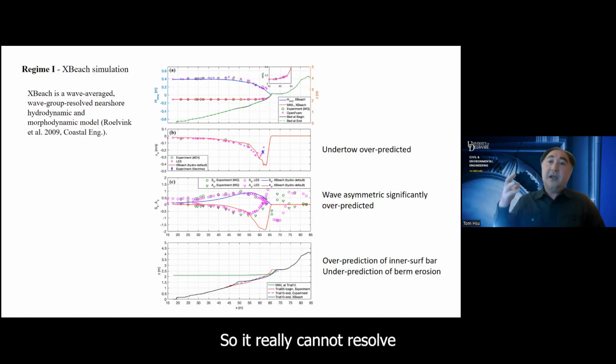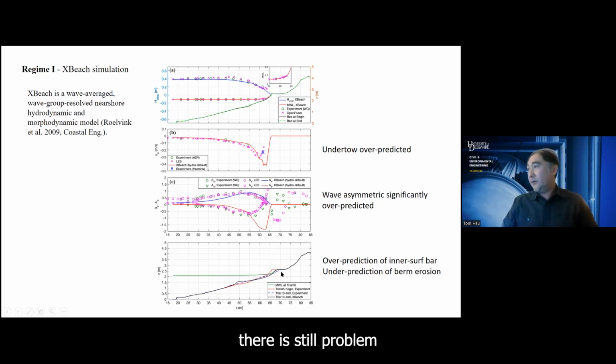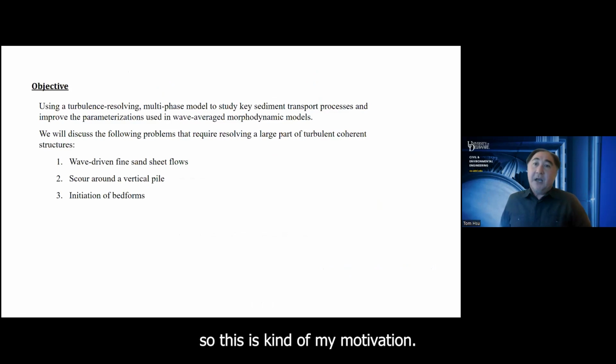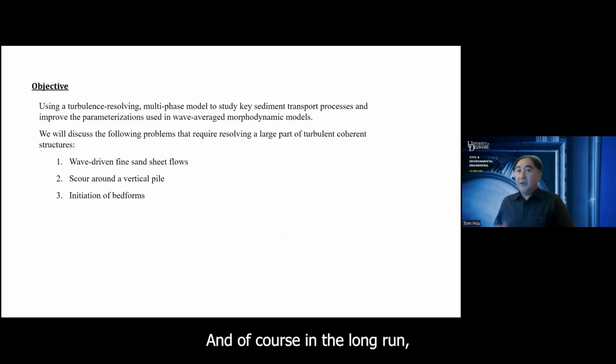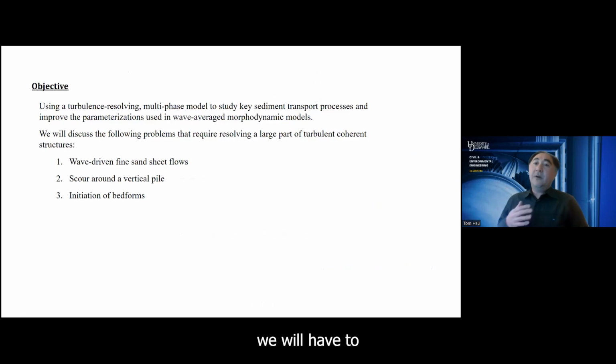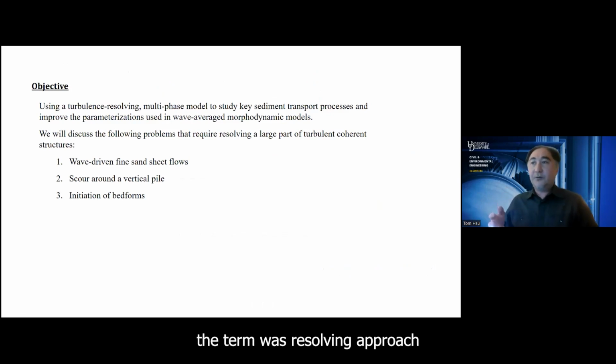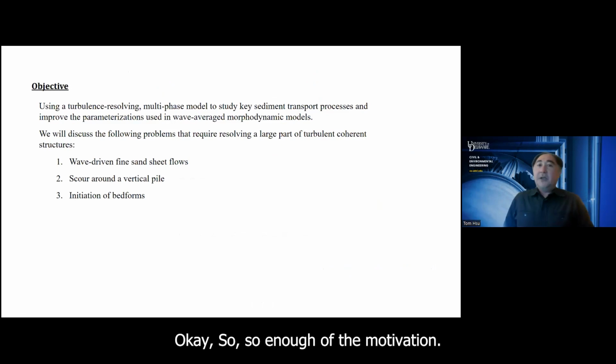So it really cannot resolve intra-wave processes and the turbulent processes. So we hypothesized that XBeach didn't do a good job of taking care of the effect of wave breaking turbulence on the sediment transport, and therefore there's still a problem with the predicted bathymetry. So this is kind of my motivation. And of course, in the long run, if we want to deal with this problem, we will have to rely on a turbulence resolving approach that really resolves the breaking wave turbulent coherent structures and how they interact with the seabed. Okay, so enough of the motivation.